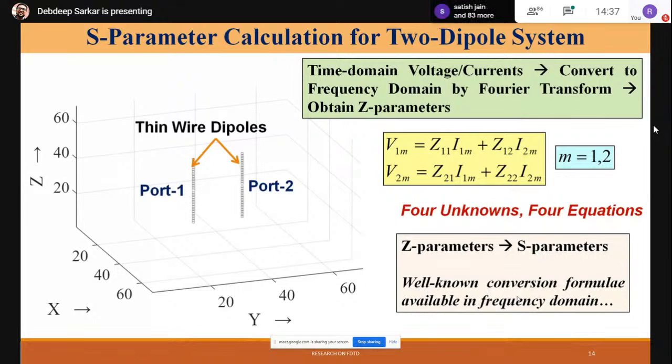book on microwave networks, where if you know the Z matrix, in this case a 2x2 Z matrix, you can find out the S matrix, and for this system we consider 50 ohm to be our termination impedance. But keep in mind that for the update equations we had, we did some transformations on the field. If you remember the discussion from yesterday's lecture, we divided the electric field by eta naught. So in terms of the impedance also, when I say that I put the 50 ohm termination, I adjust the boundary conditions such that it is basically normalized with respect to free space over here.